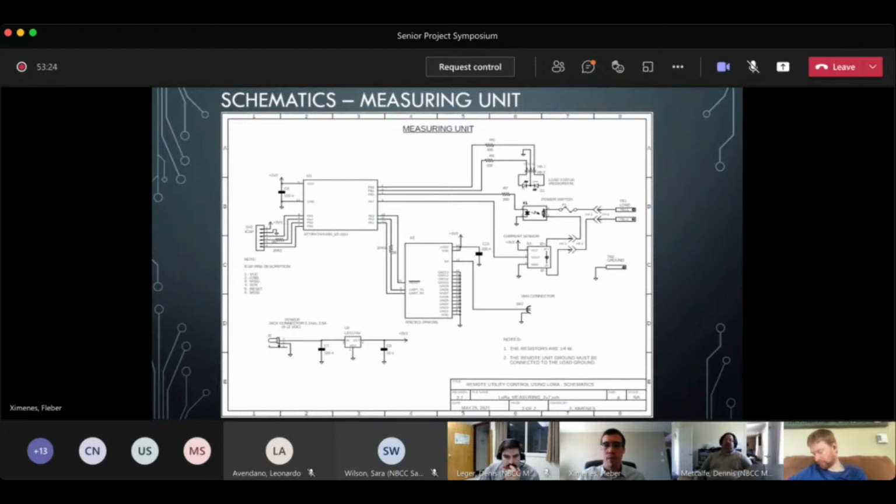My question really was what you alluded to at the start, where you're looking to isolate. Because if you were looking to isolate, your circuit fails at that. From the optocoupler, you're tying into your current sensor, which is not galvanically isolated, and then TB2 brings a ground in from your circuit too, right? So the lack of galvanic isolation is obviously apparent there. So it was defeated for sure. Yeah, all right. Well, that's fine. Again, the optocoupler was a solution that worked for you. It's not typically the solution we use it for in the case that we don't want isolation, but that's fine.